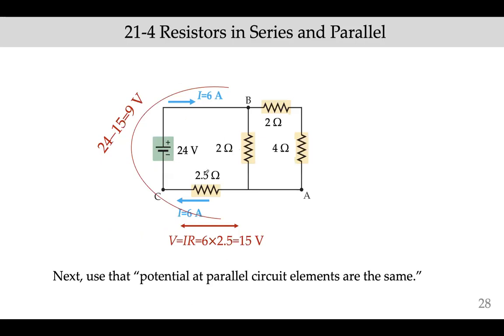Okay, so if we have 16 volts here, and if we have 24 volts here, so remember this 15, it's a resistor, it's not a battery. It uses some of the voltage that this battery creates. So 24, here 24, here 15. So if you consider the voltage from this point to this point, it will be 24 minus 15, which is 9 volts. So here we have the voltage difference is 9 volts.